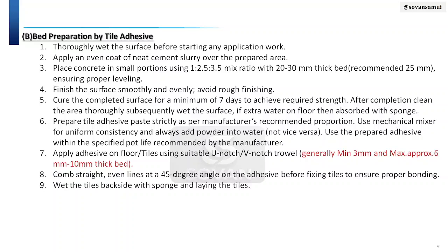And finish the surface thoroughly, and keep in mind to not do a rough finish. Okay, ensure to not rough finish. And after that you cure that place at least seven days for properly gaining the strength. After completion, you should again clean the surface, wet the surface, and apply a